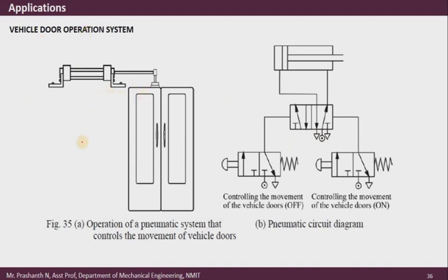Another application you may come across is the opening and closing of doors with the help of pneumatic systems. You may find these types of systems in buses or in malls, wherever you would like to control the opening and closing of doors. Here we make use of pilot operated direction control valves.